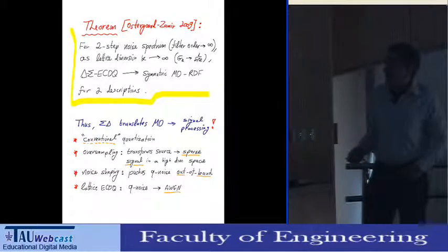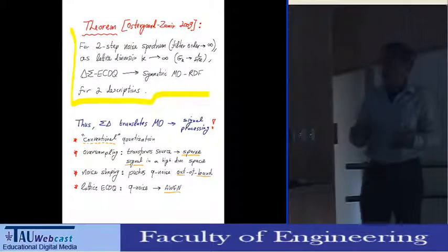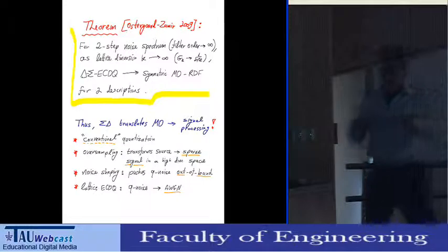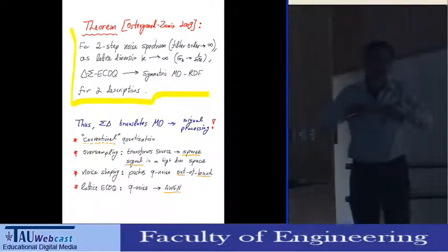We can think about the oversampling in general as taking a source, even an IID source or a memoryless source, and transforming it into a sparse signal in a higher dimensional space. This is what we did by the oversampling. The noise shaping makes sure that most of the noise is going to those dimensions where the source doesn't exist.